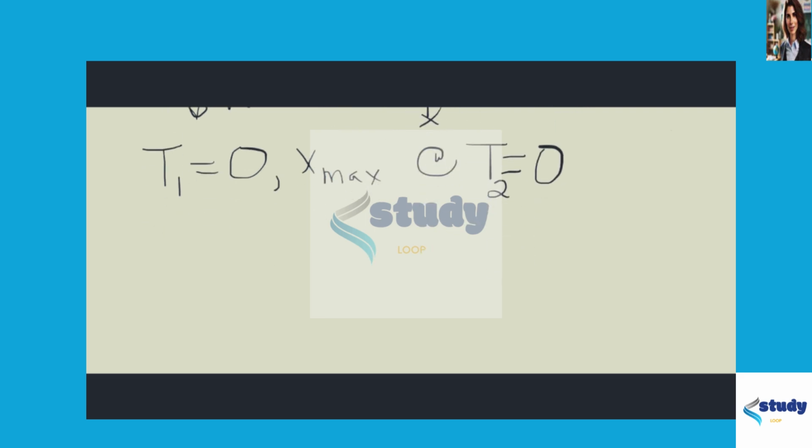Now this simplifies our computation a bit, because now all we have to worry about is the U term from 1 to 2, and that is the work done on the block from 1 to 2, or the spring from 1 to 2. And following convention, this is going to be equal to 1/2 kx squared. Now this is the energy in the spring, minus the energy from the weight of the block.